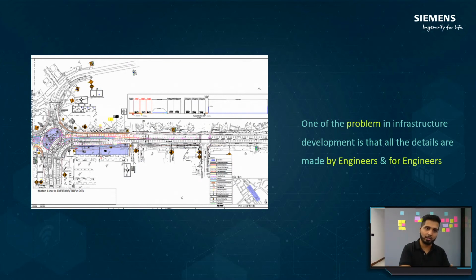When it goes close to the first junction, it will know, okay, there is a crowd here, I need to reduce speed. But sometimes that's not efficient. In the dark, it raises more questions about safety. So what we are trying to do is have infrastructure throughout the cities, like lidars, radars, and computer vision cameras, which would tell all the autonomous vehicles in this whole zone what important things are happening. So every autonomous vehicle in that zone will know what is happening around the whole intersection, or the whole area. If the area comprises maybe 12 or 13 traffic junctions, they will know what is happening around this whole area, so they can take better decisions.